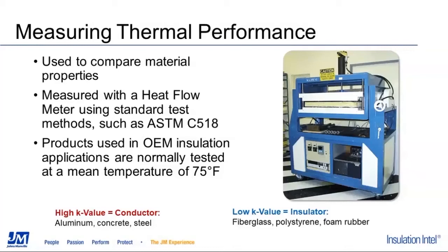Just a point of reference, there are 3 different ways that people would talk about thermal performance. That would be thermal conductivity, which is standard for 1-inch thick product, thermal conductance, which varies based on product thickness, and then sometimes you'll hear R value, although that's more discussed in building type insulation. R value is just the thickness divided by thermal conductivity.